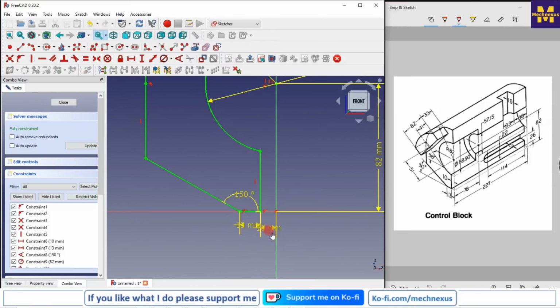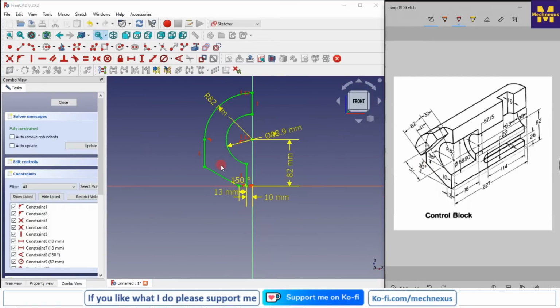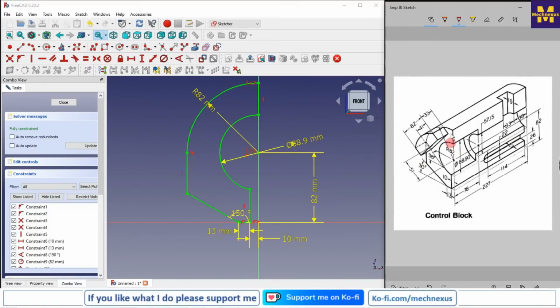Now I will move my dimension for better visibility to check my profile. So here is 10, 13, this 30-degree angle, and this outer diameter, or we can say R82, the outer radius, and this inner diameter is 88.9. So here our sketch is constrained.